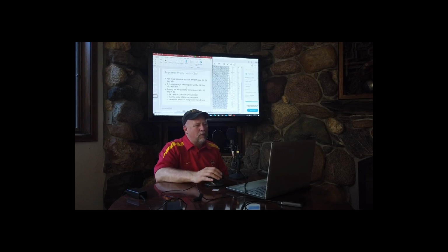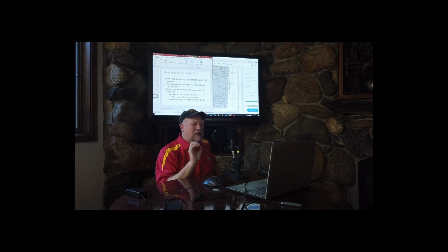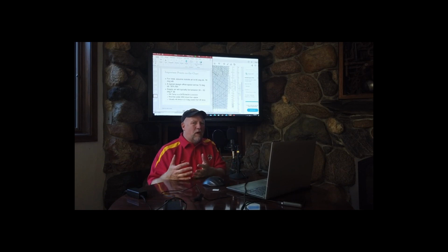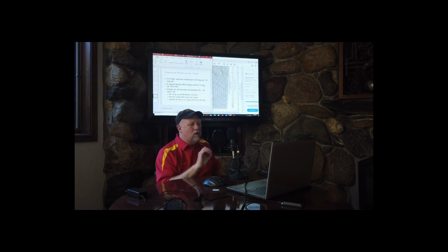All right, and then some important points. Like I said, for Iowa, assume the outside air temperature is 95 degrees Fahrenheit dry bulb, 78 wet bulb. Typical design office and classroom spaces, 72 degrees dry bulb, 50% relative humidity. Supply air is typically between 50 and 55 degrees Fahrenheit, and supply air is a designer's choice. In other words, we pick what equipment we're going to buy. This supply air must be cooler and drier than the space.